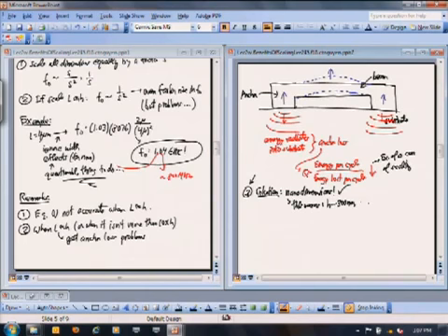Okay, so we're talking about a wireless application, right? In wireless communications, you're receiving a signal at your antenna, okay? And that signal that you receive at your antenna usually is a pretty small signal. So probably this nano resonator can handle that signal, okay? But the problem is there could be people around you transmitting much bigger signals. In fact, the wireless problem is that you're trying to receive a signal from a faraway cell tower.